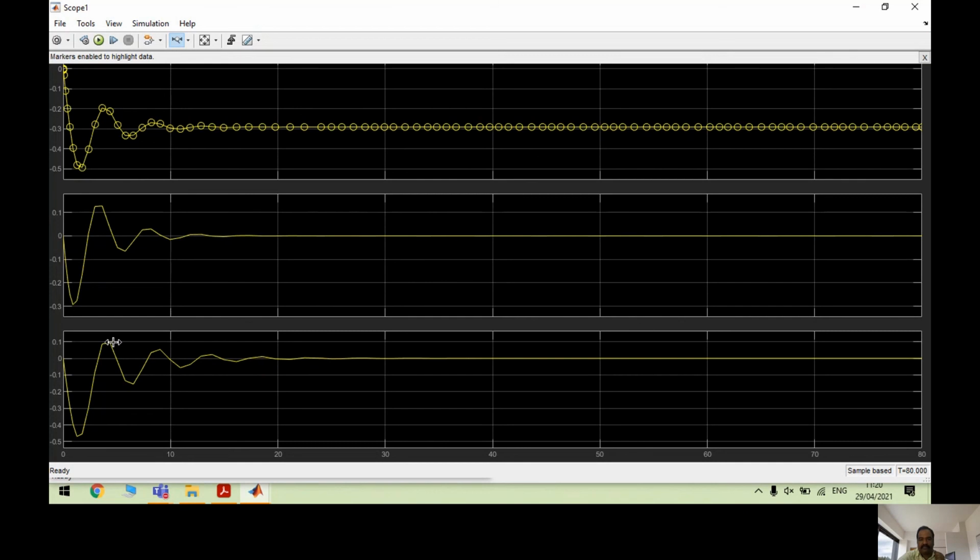The initial transients will be a little bit larger. This is what we call a peak value, and this is a settling time. Both are a little bit higher. Settling time, peak time will be higher, but my steady state error is 0. If you are more bothered about having your 0 steady state error, it's better to go with an automatic PI controller.